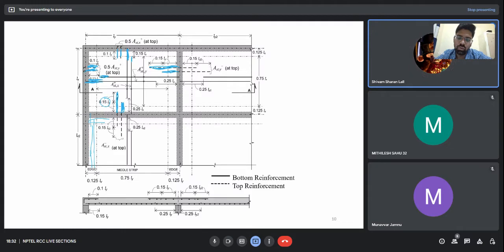Okay. So my question was, for that M20 grade, tau c value, then we'll go for that value only. No, we won't go by that value. That's what this distribution reinforcement is for, because shear reinforcement is predominant at the edges, if you know. And to satisfy those shear requirements, or to satisfy the minimum area of tensile reinforcement, we provide these bars.